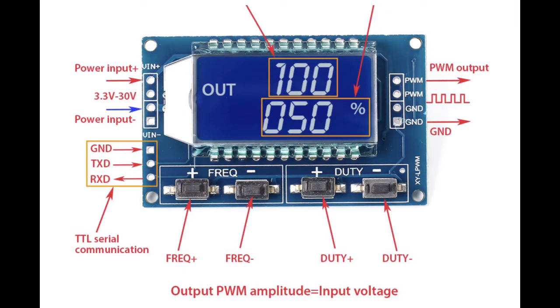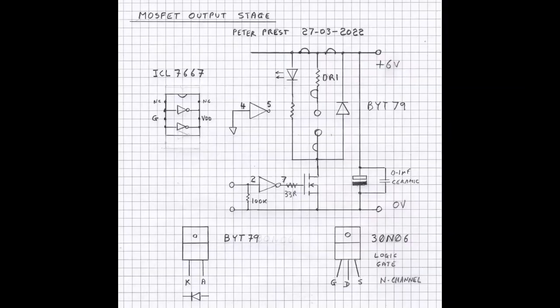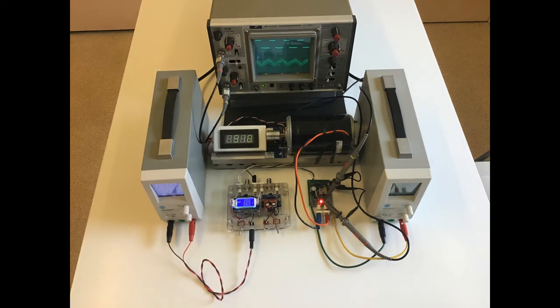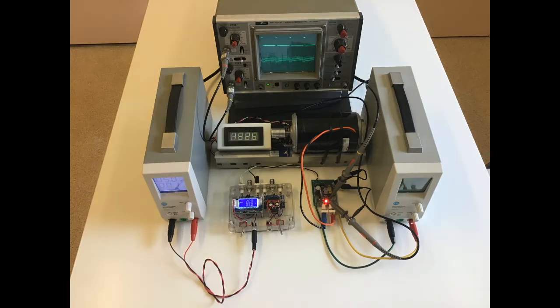These clips use an eBay PWM generator set to 20 kHz, the same frequency as the Uni 8. Three different duty cycles are shown: 40%, 60%, 90%. They demonstrate that although the voltage is PWM, the current is significantly smoothed by the inductance of the motor, so our voltage control principles still apply.